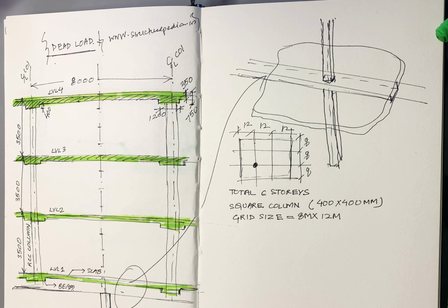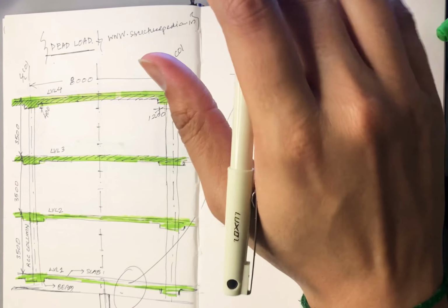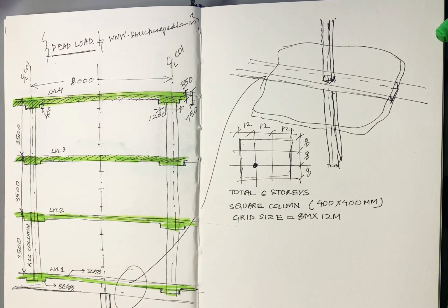I will discuss the conceptual design that I have done for a building and how to select beams, where to select beams, and the bedroom, toilet and kitchen layout. You need to be very careful with the levels. It's not easy to fix a conceptual design, but once you have done that, it is very easy to go towards the detailed design.